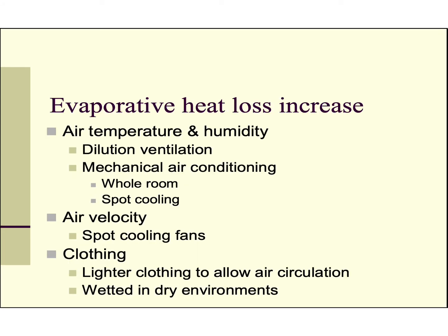How do we increase evaporative heat loss? Well, you'll notice that most of this is about the same as the convective heat loss considerations in terms of ventilation and air velocity. One significant difference here is clothing, and particularly that in dry environments sometimes the clothes can be wetted, so that it's not just sweat that's causing the heat loss, but also the evaporation of water applied to the clothes. Obviously, in more humid environments, this wouldn't really do any good, and the other measures, particularly the mechanical air conditioning to reduce both temperature and humidity, would be more effective.